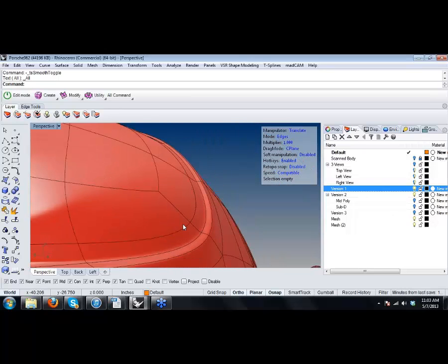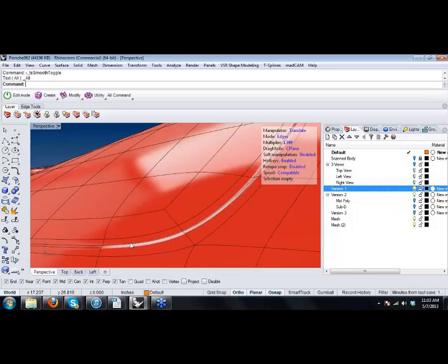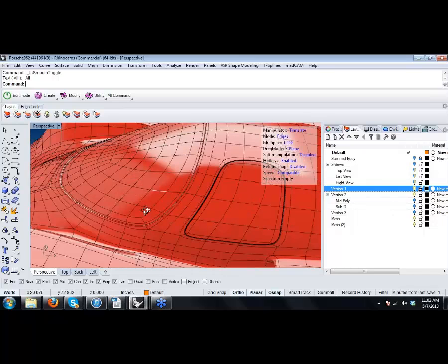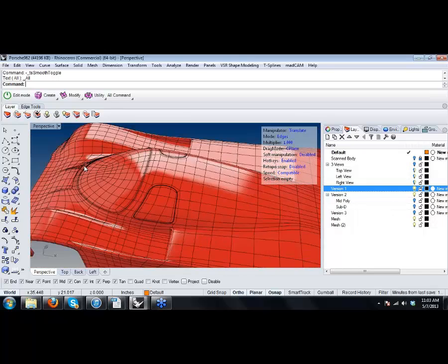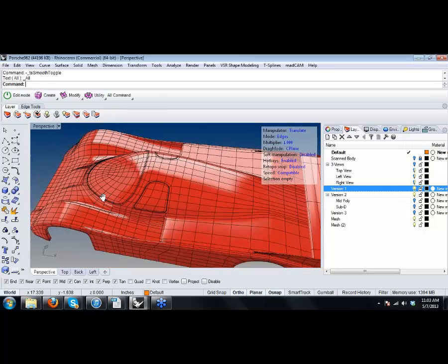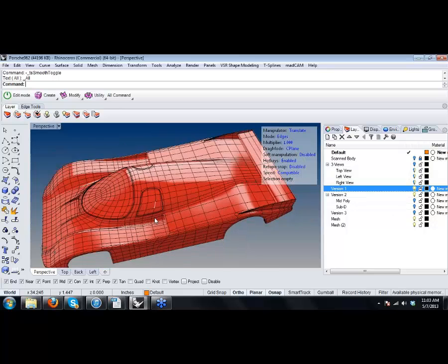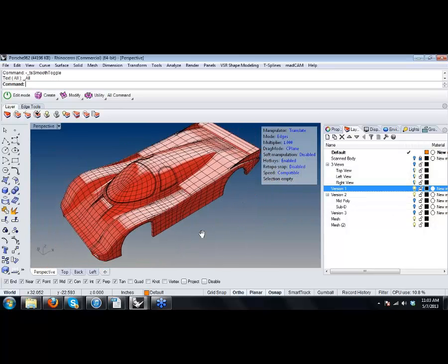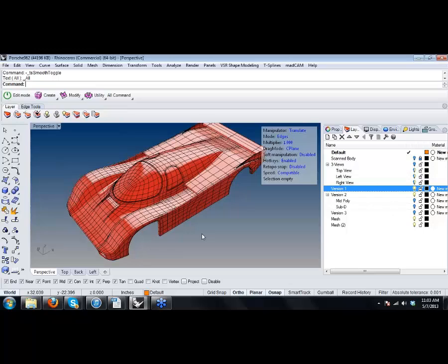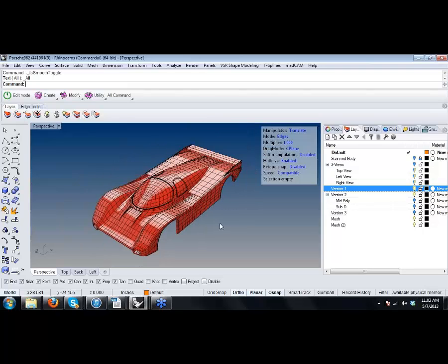And while there was no point in doing this sort of return for the windshield here that I did, at the same time, the overall approach to doing this whole cabin as one T-Spline is totally legit, and I would completely recommend it. So this is an interesting mix of things that I would now still use T-Splines for, and things that I would absolutely not recommend using it for. Yeah, I think that's about all I got to say about this.